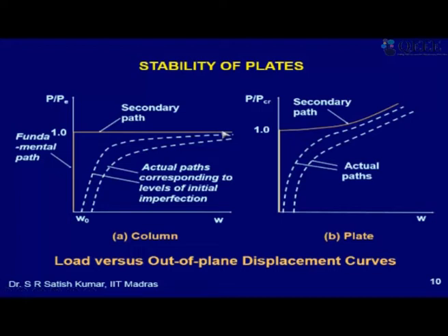So that is an unstable buckling of a perfect ideal column, but practical columns do have some imperfections. So they start buckling from the beginning, but they don't lose their stiffness so quickly. So as I approach the critical buckling load, they lose their stiffness and they go asymptotic to this curve. Okay. So these are actual buckling curves for practical columns.